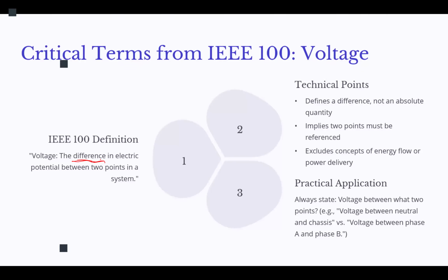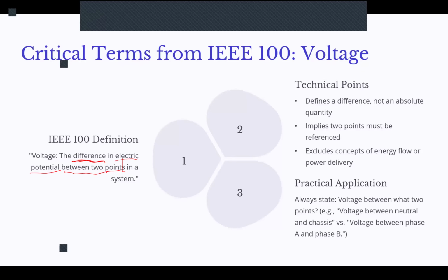One example is the casual referencing to batteries. When you want to say how strong the battery is, you say this is a 3-volt battery or a 9-volt battery. That's basically nonsense, because that number is the potential difference between the 2 poles of that battery, not the energy, not how strong that battery is. I wanted to give you an example of what I mean based on this terminology. Next, it always defines a difference between 2 points in one system. So you cannot simply say, the voltage at point A is blah, blah.